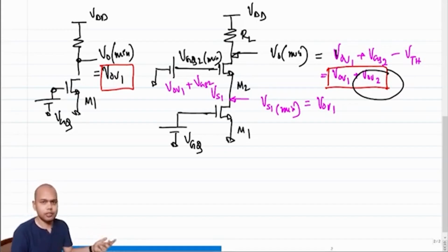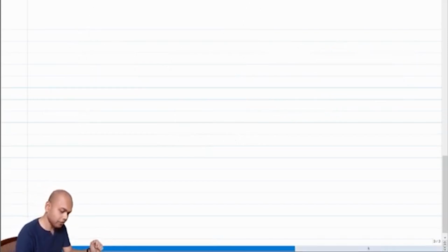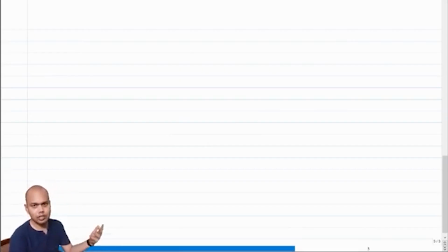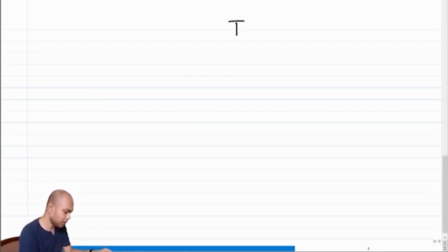Because we have seen earlier that a constant voltage bias has issues, right? It's not a very robust way of biasing a transistor under the condition that the ambient voltages, temperatures, and everything can change. So essentially, if threshold voltage changes, then what happens? So what is an equivalent threshold voltage independent biasing scheme? That's what we are asking.